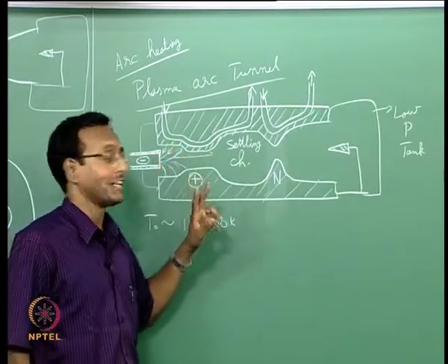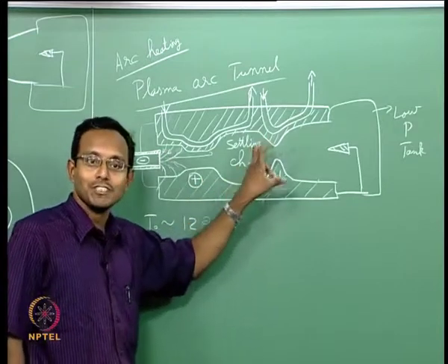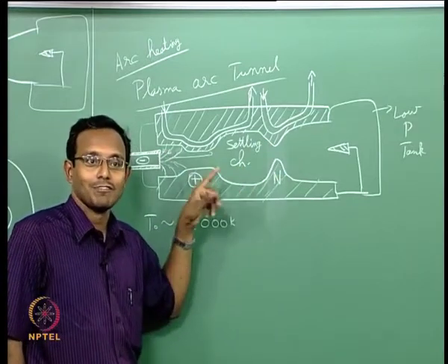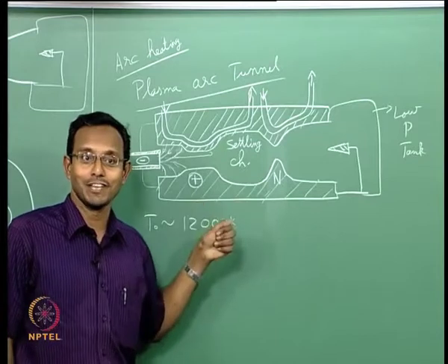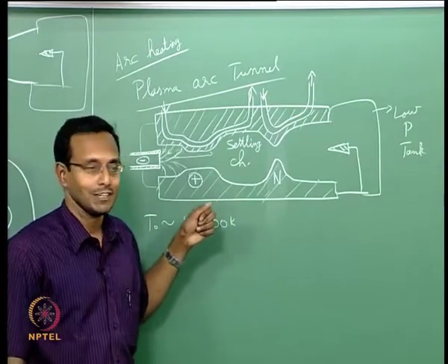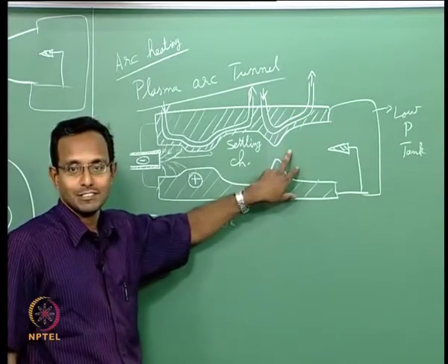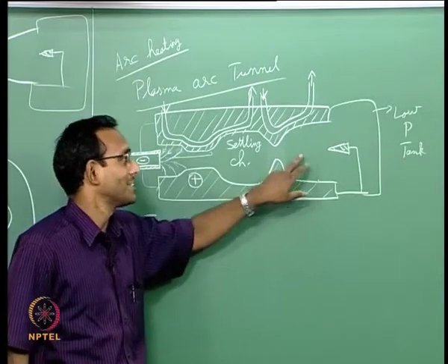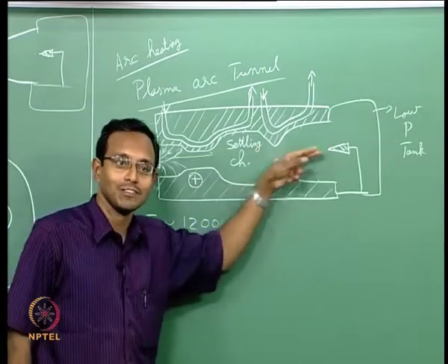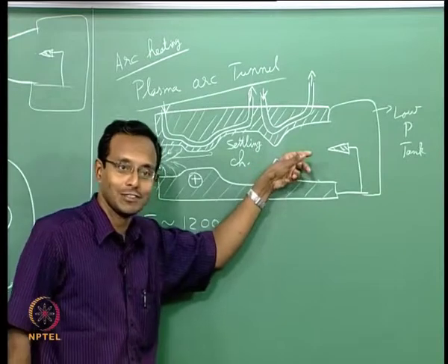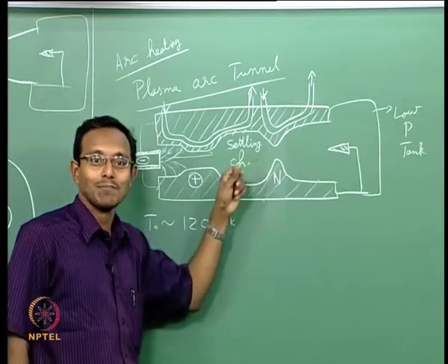Okay. If that is the case, then because of this recombination, the gamma of the gas will change, the molecular weight of the gas will change, average molecular weight of the gas will change. Okay. Because of all this, I will have variation in A along this direction, variation in gamma along this direction. So my flow is a little more complex now.